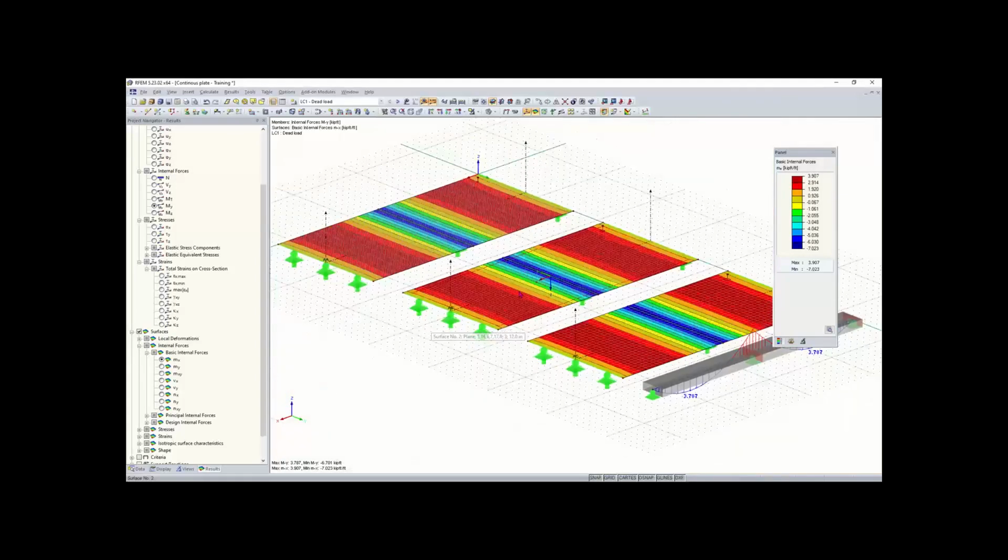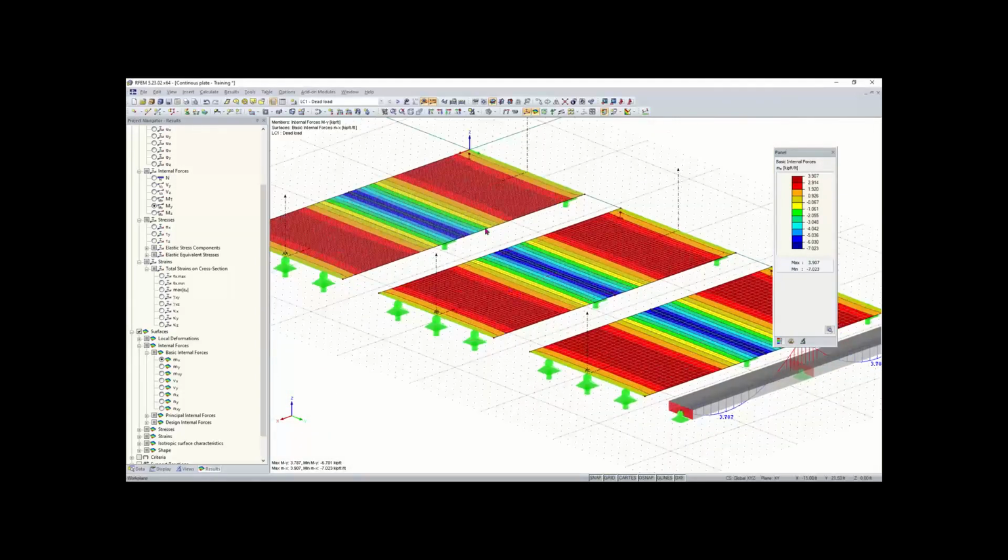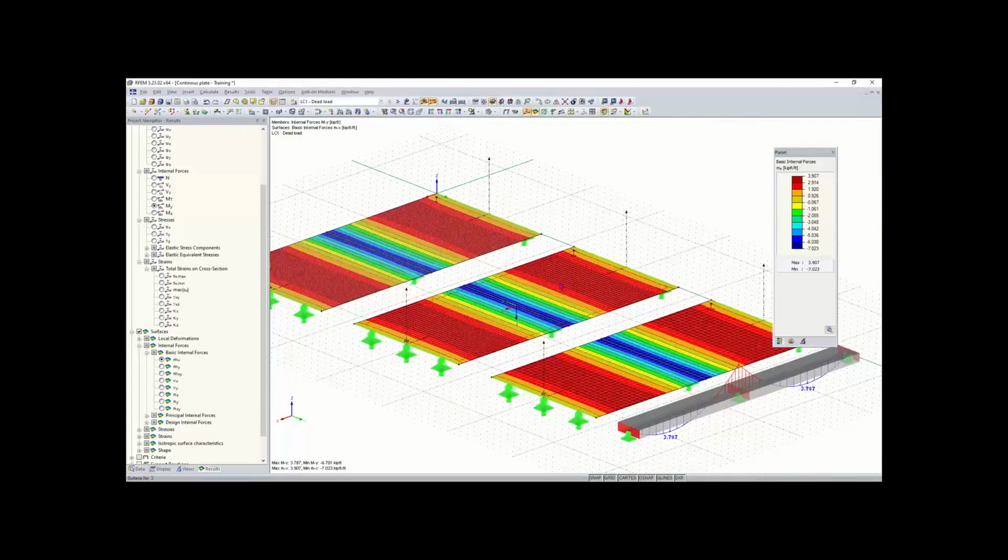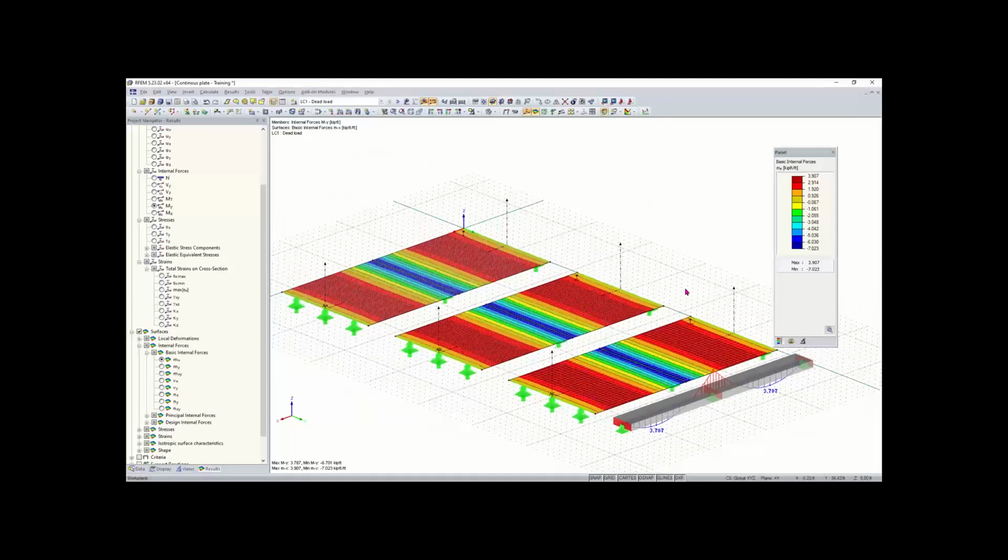But then also you can run the results of your model with a certain FE mesh length, then change the FE mesh length or make it finer, and run your results again and compare those results to see how much they've changed. You can just keep doing that until your results don't change, or the difference between your results is small.